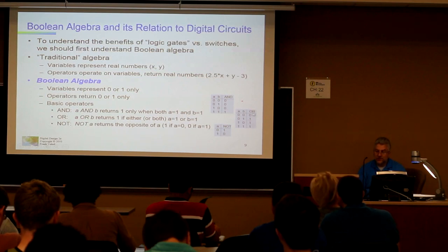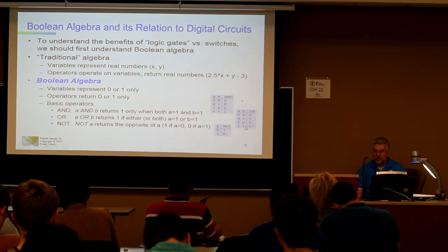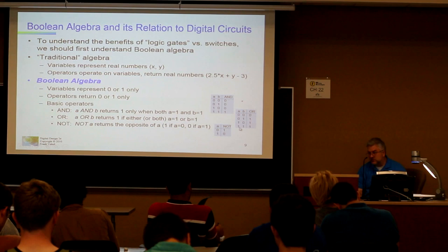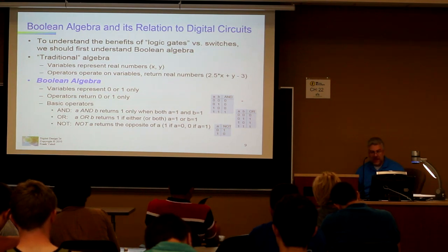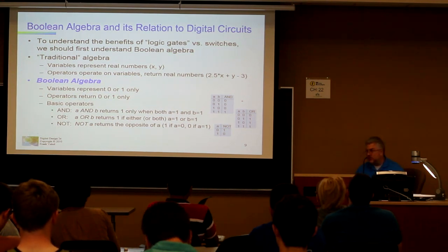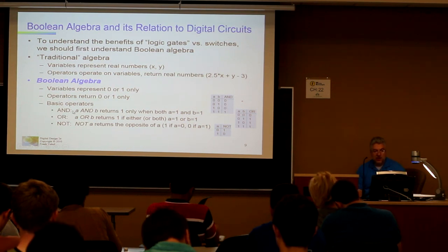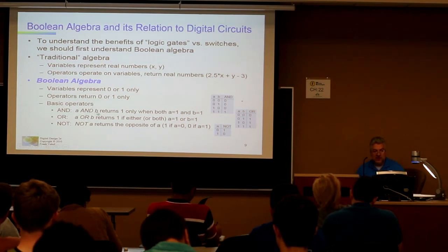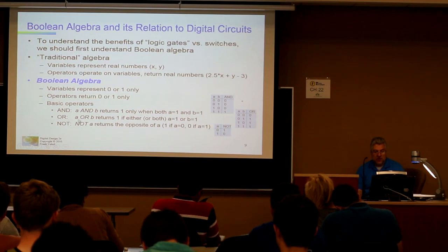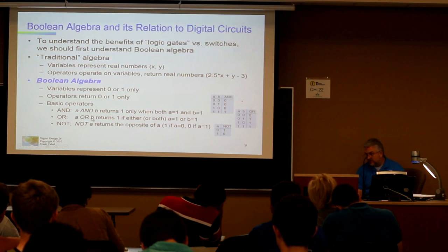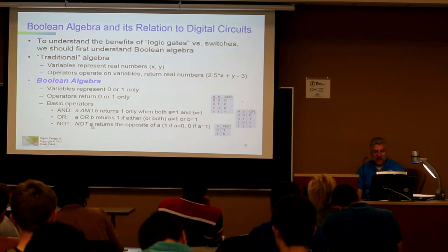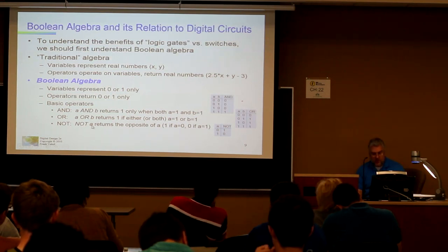And as you can see, for example, for the OR gate, when both of these are 1, well, at least one of them is 1, so your output for the OR gate is going to be 1. And when I mean output for the gate, I also mean for the Boolean algebra aspect of this too. So in the Boolean aspect, we would say A and B, or we would say A or B for the operation of the OR, and then you would say NOT. But we also have another way to represent this.